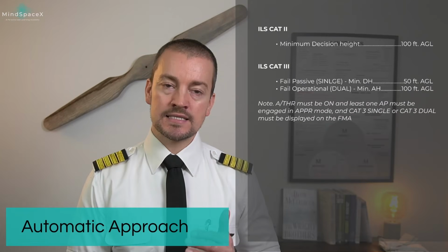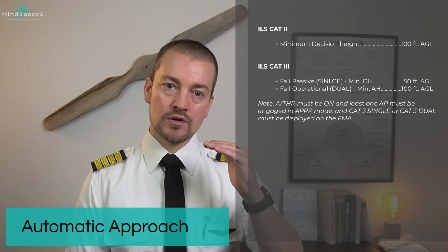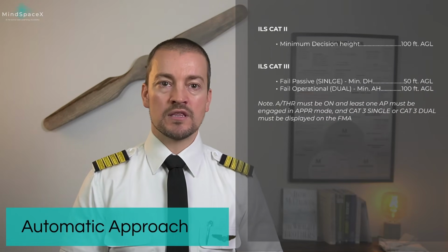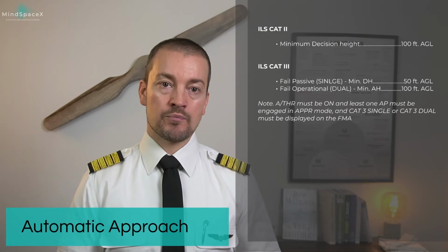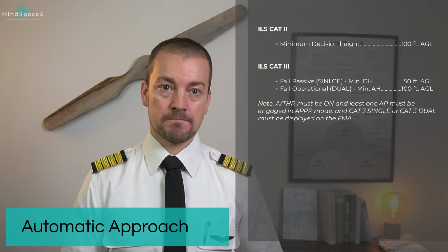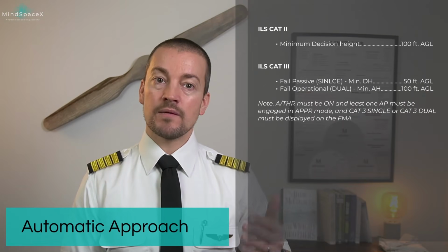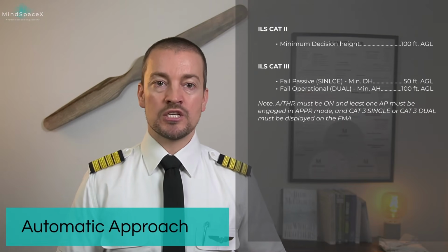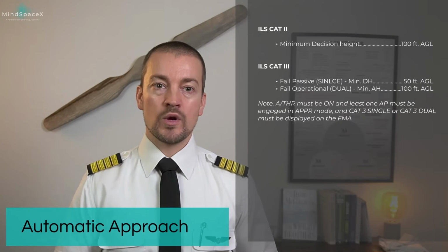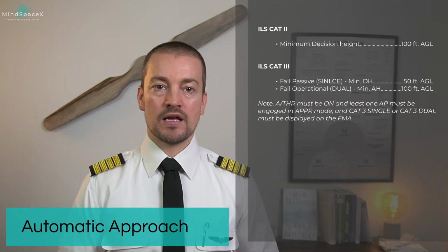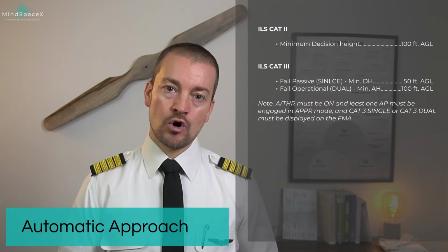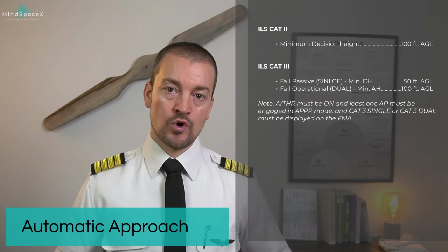A decision height is set so pilots have to get and establish visual contact with the environment, with the airport runway, approach lighting system, etc., prior to commencing the landing. If you don't have that by the time you reach decision height, you must initiate a go-around. You are not able to land. With autoland, we have the capability of landing without seeing the runway in front of us. But the capability of the autoland depends on the systems, of course, working.